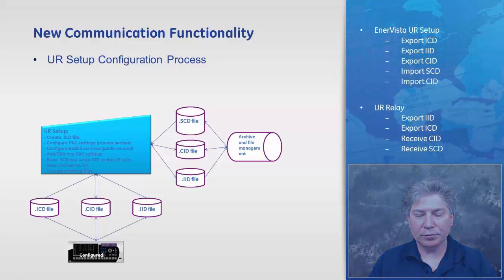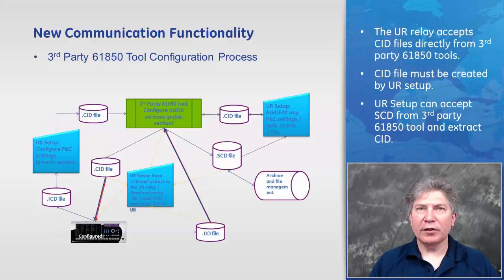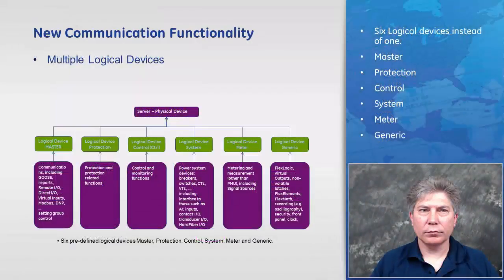The UR relay will accept CID files directly from third-party 61850 configuration tools if the original CID file was created from the UR ICD file. The UR Setup program can import an SCD file from a third-party 61850 configuration tool, strip off the UR portion, and write the CID file into the relay.